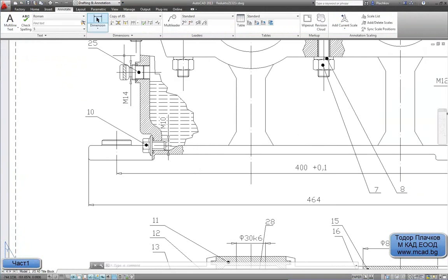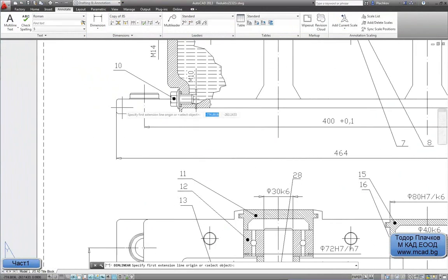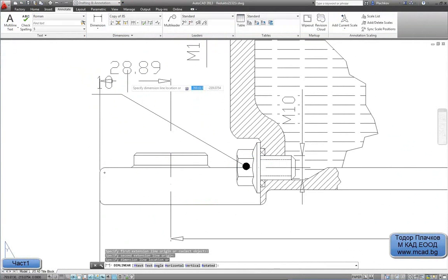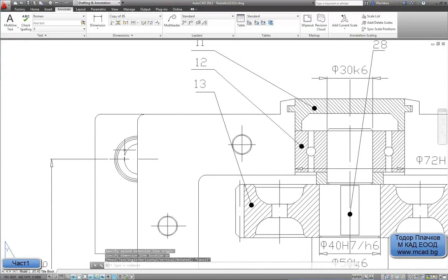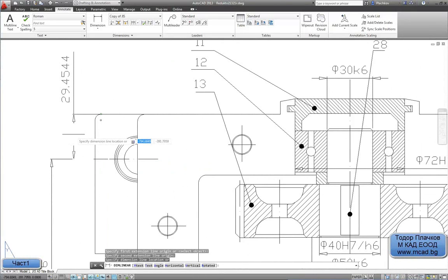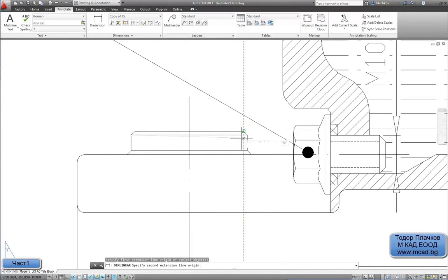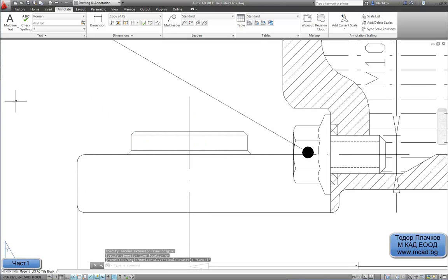The next step is these cylindrical solids right here. I think they are one of the few parts of this solid which are correctly dimensioned. It is 30 to 30 from the corner of this, and the height is 30. Okay, the diameter is 30, and the height is 6 millimeters.